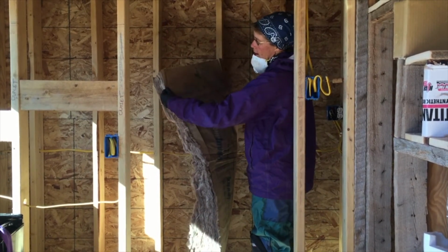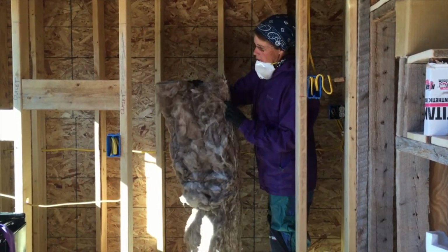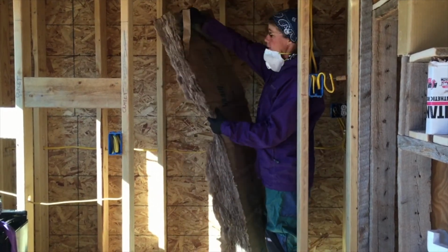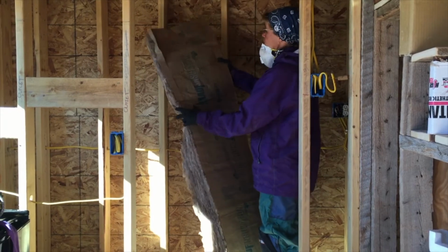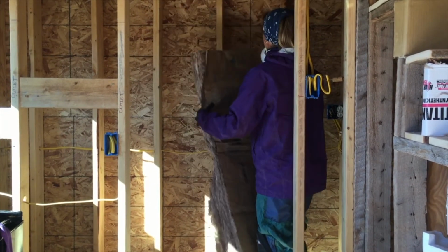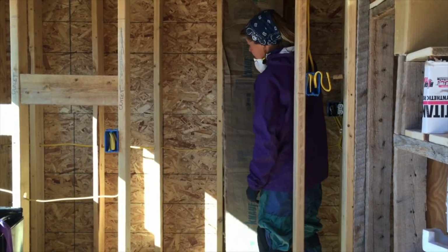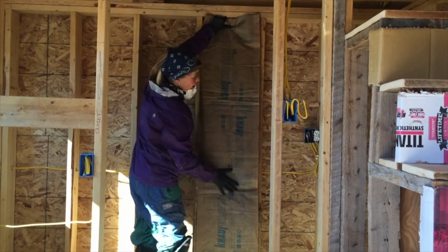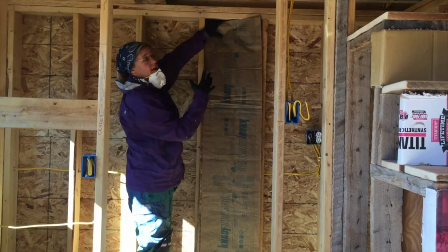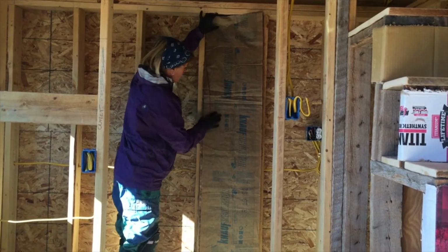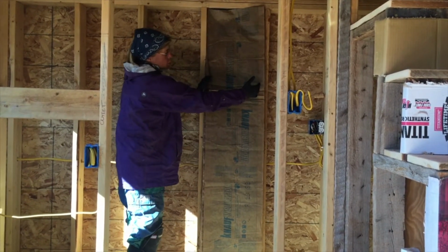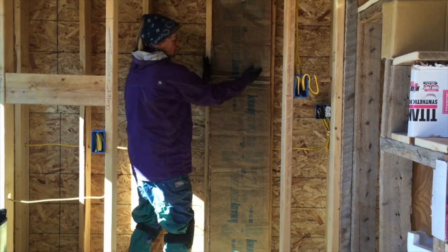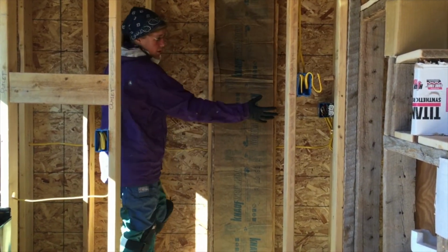Insulation has these flaps to staple to. This is fiberglass insulation. I want the paper facing inside unless there's some specific reason I would have it facing out. I have cut my batt to length. What that means is I'm trying not to have a gap at the top or the bottom. We framed our building as much as possible for either 16-inch insulation, which means our studs were 16 on center, which they make insulation to fit these bays, or we did 24s.